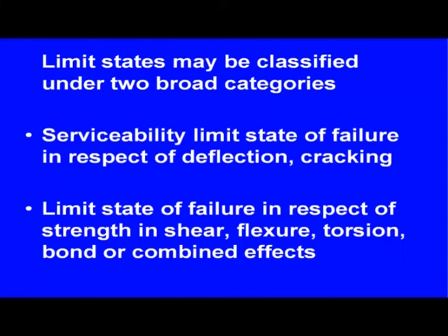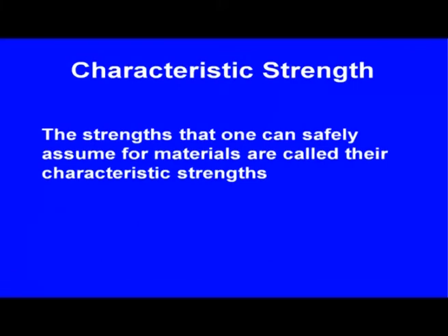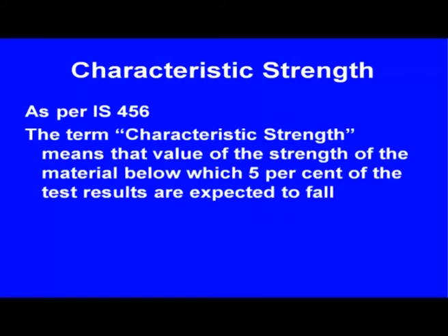The first one is the characteristic strength. If you say M20 grade, FCK is equal to 20 Newton per square millimeter, and M25 grade is 25, measured 28 days after completion. The design strength is 0.67 FCK. Again, why are there two levels that you are giving designers? Two-thirds of that we will use from the material's point. Two-thirds into two-thirds is 4 by 9, or 0.4 FCK.